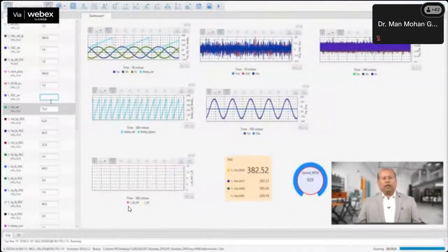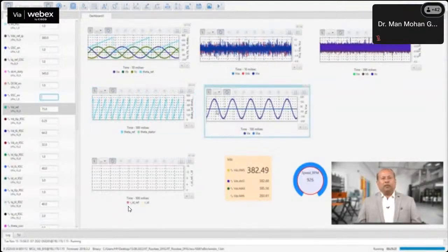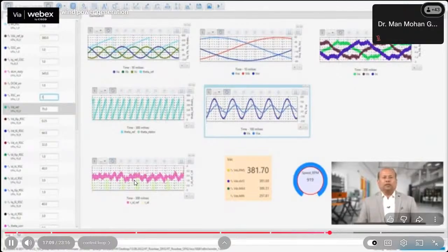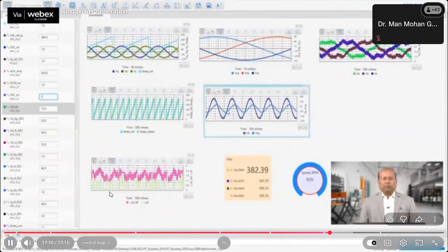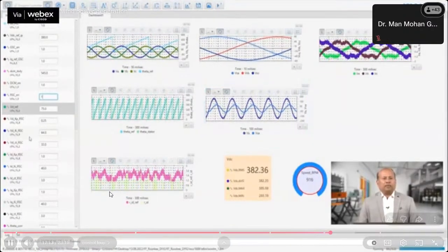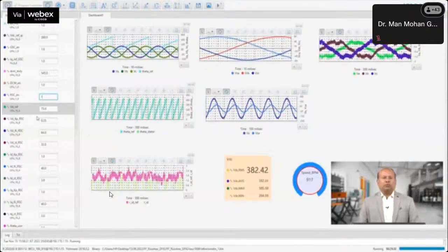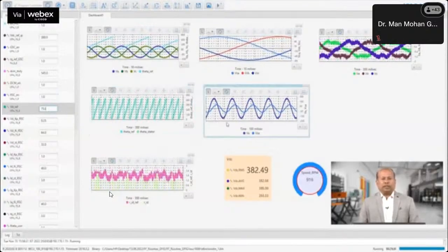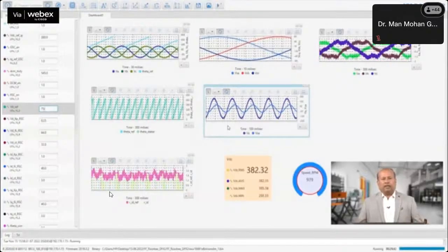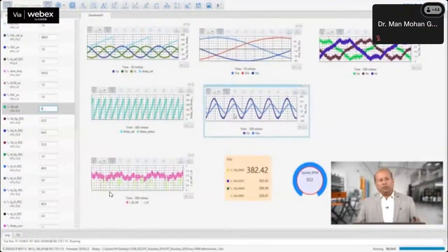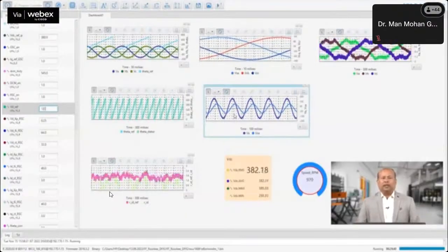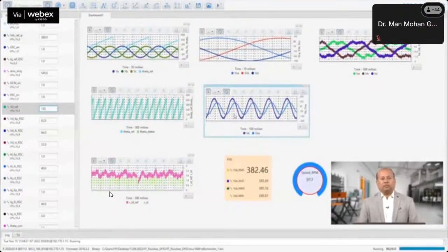Next, we provide the PI value of the rotor side control and enable the control loop. The RSC first is used to build up voltage in the stator side and then match the phase difference of the grid to the stator till they align for the synchronization purpose.